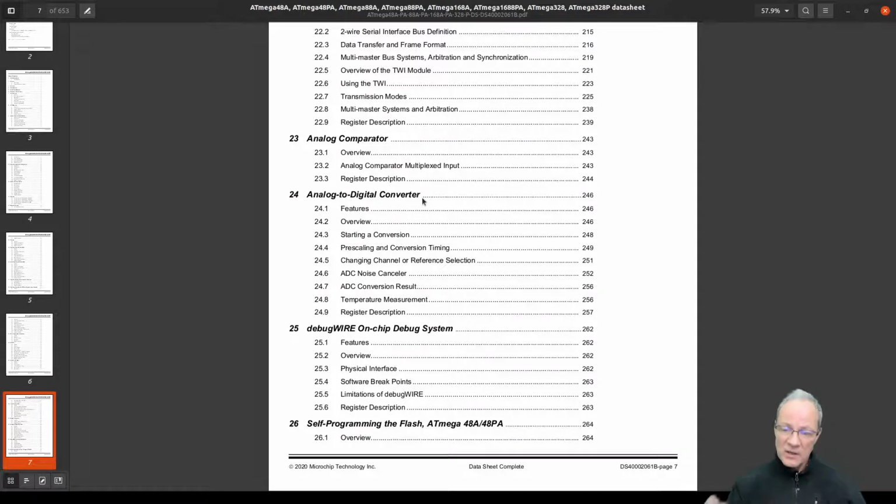So that needs to be converted to digital, to numbers basically, so that we can do some computation on them. That's what the ADC device does. That's built in, right? Of course, if you want to use that, you need to know how to actually program it, how to start it, how to know when the read is done, so it's not instantaneous.